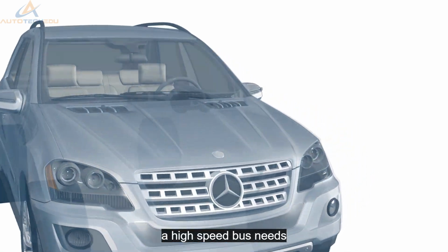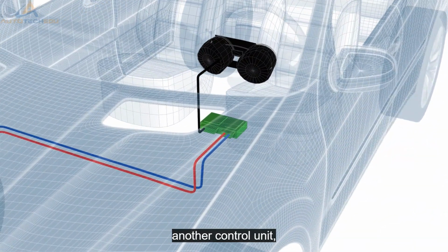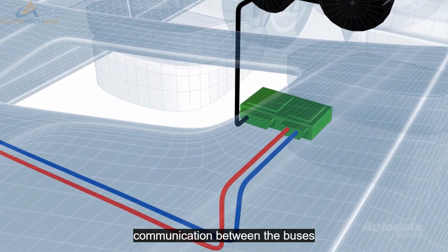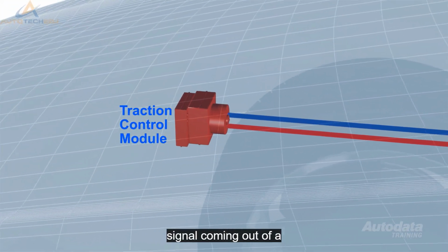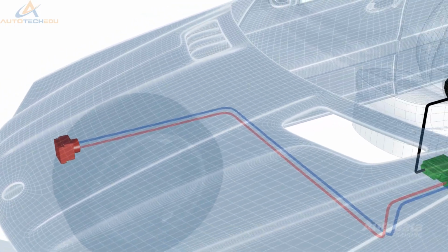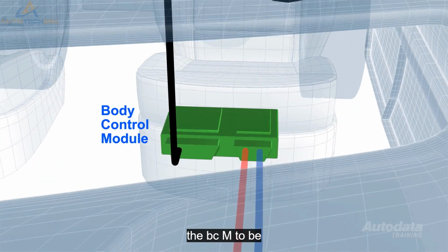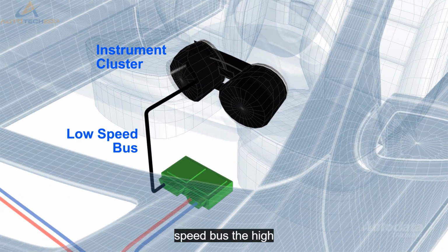If a high-speed bus needs to send a message via a low-speed bus to another control unit, it needs to go through a gateway. This allows communication between the buses. For example, if a high-speed signal coming out of a traction control module needed to get to a low-speed bus, it would have to go through a gateway, which in this case is the BCM, to be able to get to the instrument cluster via the low-speed bus.